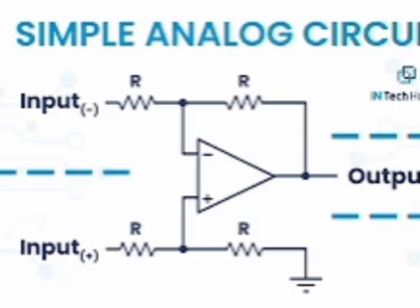Input impedance of second stage Zin2 equals beta 2 RE. Input impedance of first stage Zin1 equals beta 1 beta 2 RE. AC Thevenin impedance at input RTH equals RS parallel with R1 parallel with R2. Output impedance of first stage Zout1 equals RE1 dash plus RTH by beta 1. Output impedance of second stage Zout2 equals RE2 dash plus, numerator part RE1 dash plus RTH by beta 1, whole by beta 2.